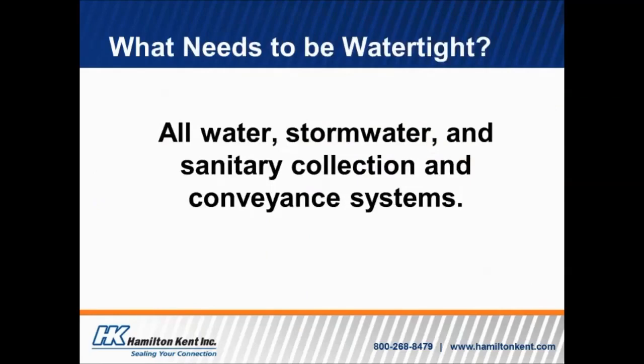So what needs to be watertight? Well, in our opinion, if we're looking at the long-term durability and lifespan of our underground infrastructure, and by underground infrastructure, I mean water, stormwater, and sanitary collection and conveyance systems, then our opinion is that everything needs to be watertight. If everything is kept watertight, then that is going to make it last much longer, as well as the infrastructure that's above it, because you're not going to have those leaks.